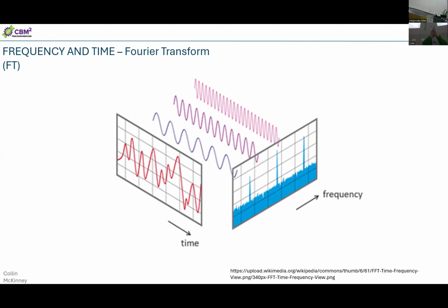differences from each other. So as you can see here, we have this kind of funky looking waveform, but it is repetitive. And I can make that waveform by taking 3 sine waves of various amplitudes and phase differences to reproduce that. And by virtue of that, the Fourier transform separates that signal out into the 3 sine waves, and you see those 3 spikes here that represent those. So we can go from a time domain signal over to a frequency domain signal and see what's happening in the frequency domain. We also automatically see that they're periodic, right?